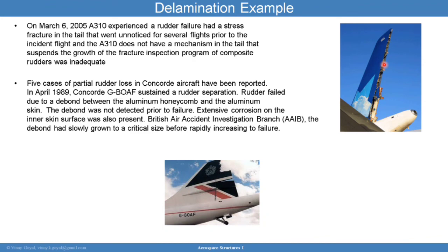But when the aircraft climbs to an altitude of 40,000 feet and you have a defect in place, the air outside has decreased, yet the air inside of the composite could remain entrapped. That pressure difference through the thickness can then cause a face sheet to blister and blow apart. There are several incidents in launch vehicle, spacecraft, and aircraft applications where this has happened.